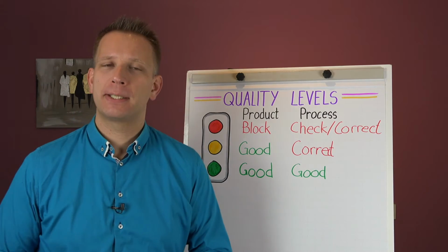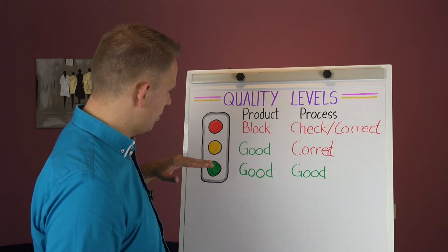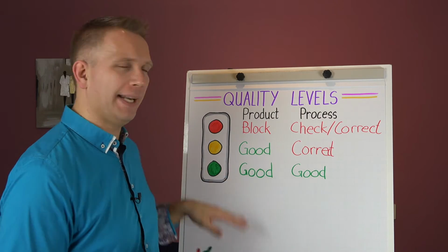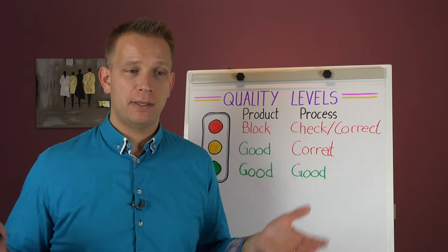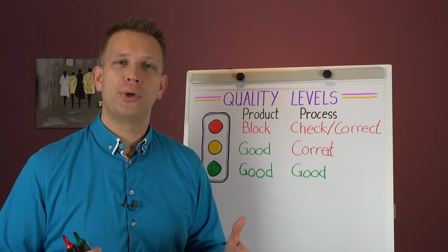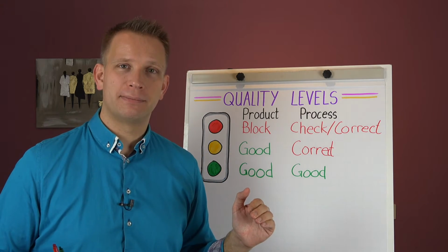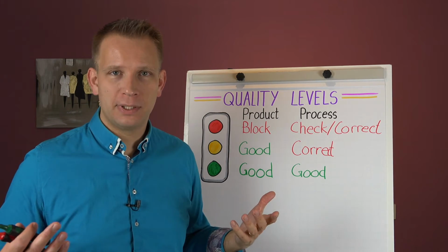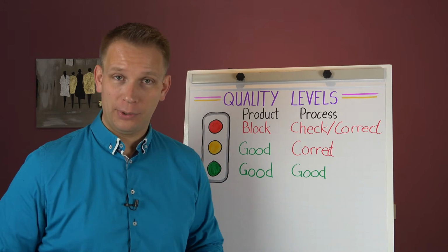And that basically becomes the quality traffic light system. So when you give operators the green, that is when both the process and the product are behaving as you expect. They're both good. So that is a moment where you do not touch anything. Then the level up, the warning level, is basically saying, okay, the product can go down line.